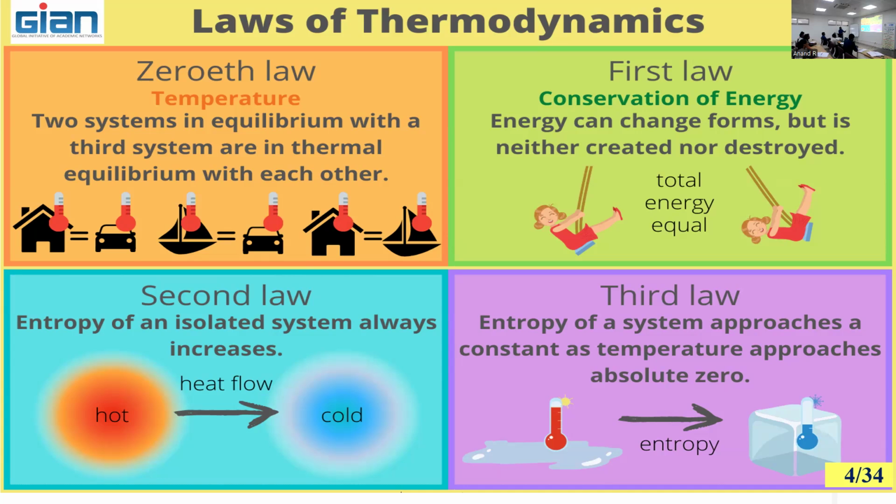The good example you can say is the internal combustion engine. You are producing heat from the fuel. The chemical energy is stored in the fuel. During the combustion, you are converting chemical energy to heat energy. Whatever amount of heat is available from the products of combustion, some percentage will be converted into work, and the remaining percentage will be heat that is going to be rejected. Without rejecting the heat, you cannot produce the work.